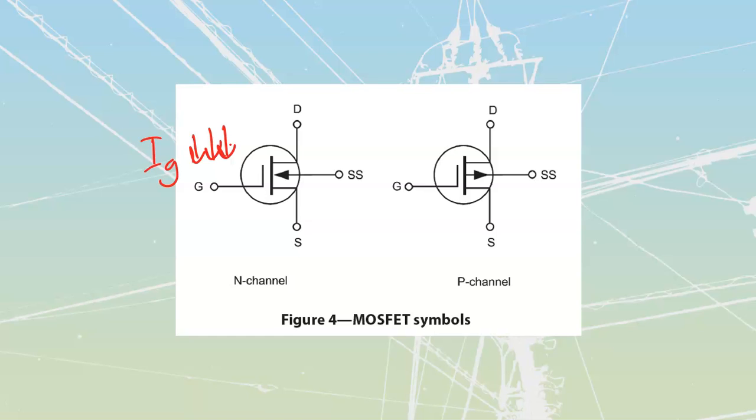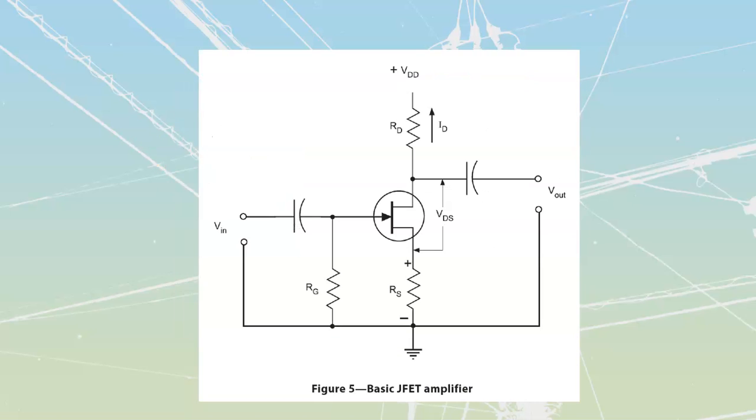But they do have some major disadvantages in the fact that they're super sensitive. Static charges, electricity that you're going to pick up by the way that you walk around, shuffle your feet, etc., can destroy these things as you touch them. So you've got to be real careful about grounding on these things, and that you are maintaining a ground on yourself with a ground strap, etc. Read through those points that they show you inside of your binder, and just be very careful when you're handling anything that is a FET, because they are so sensitive.